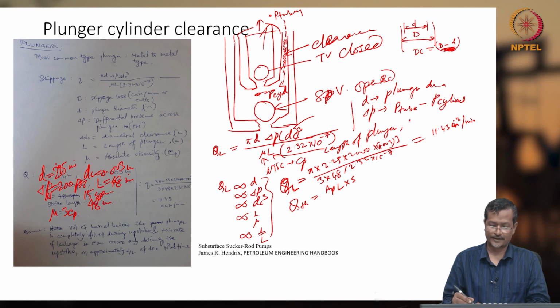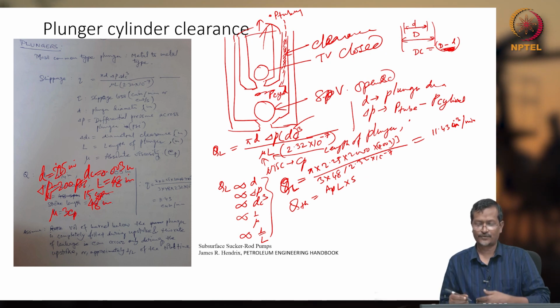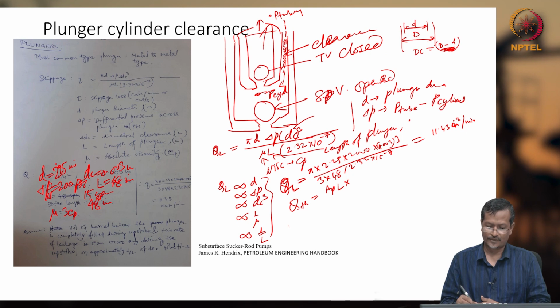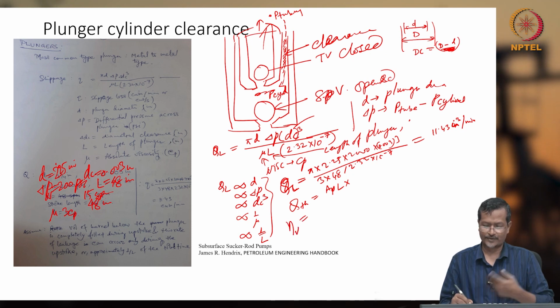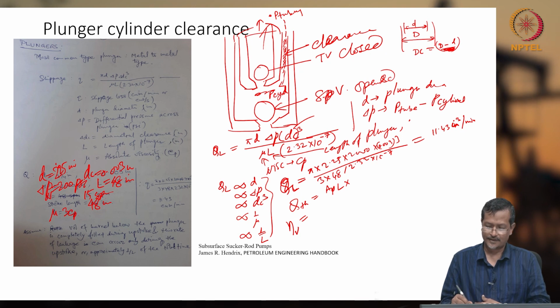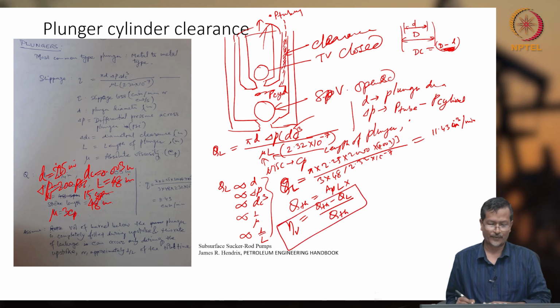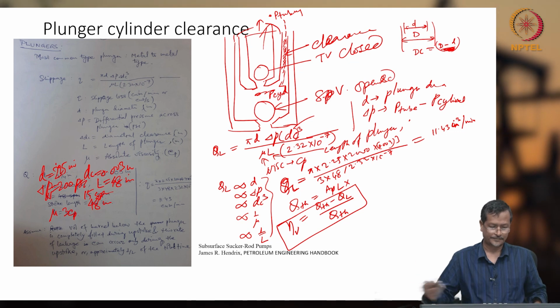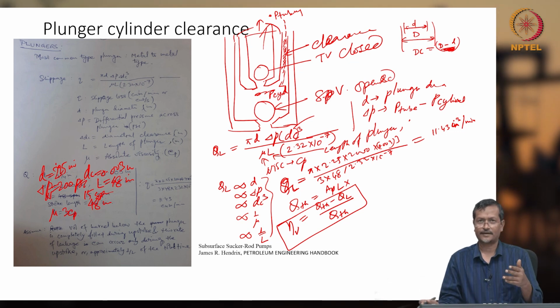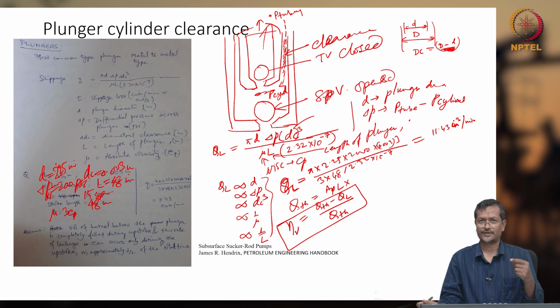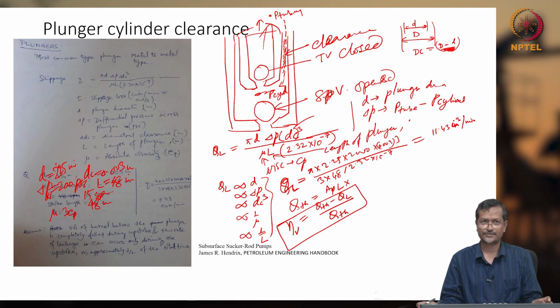So if we get this theoretical flow rate and leakage flow rate, then we can get volume efficiency, eta volume, or volumetric efficiency or EV, whatever you write. Theoretical Q theoretical minus Q leakage divided by Q theoretical. So it will be your volumetric efficiency. Okay. Now if I give different clearance or different pressure or anything, you should be able to calculate using this formula.